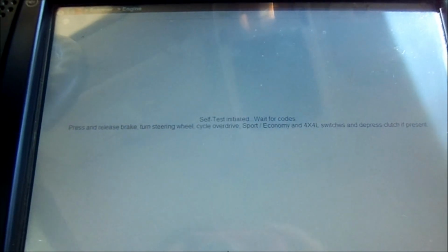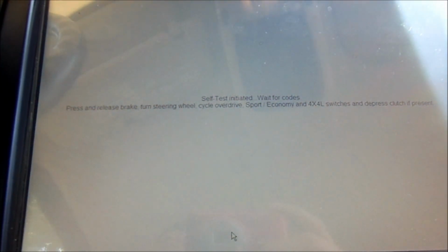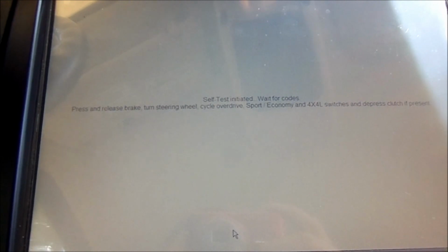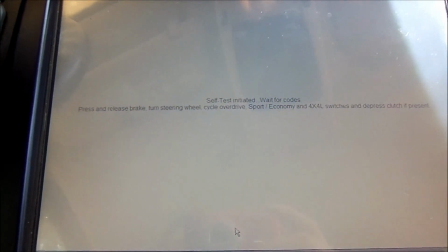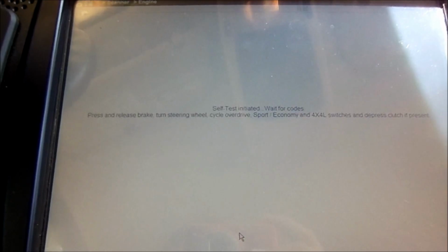and this is just to make sure that you're not going to have an issue with any of your engine related components. And what we need to make sure is working properly is our EGR sensor module. That is one of the things that will cause this P2106 trouble code to come up. Once everything passes the test here, then we are ready to just take it on the road.